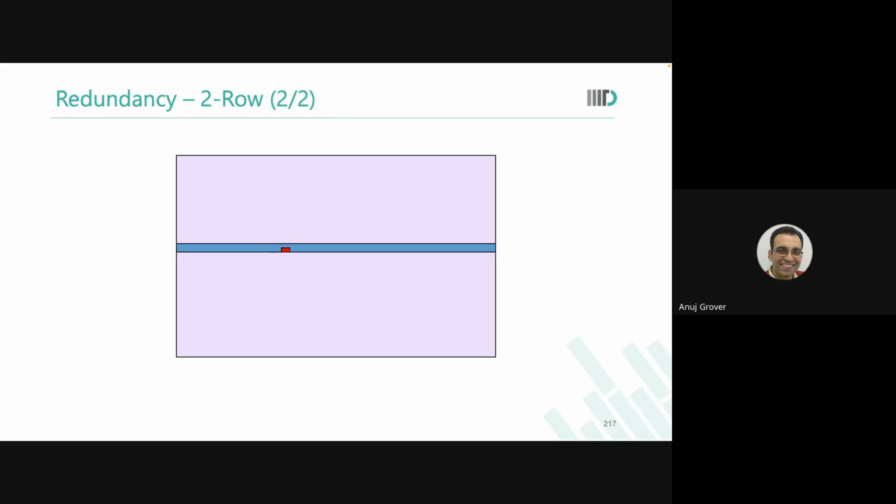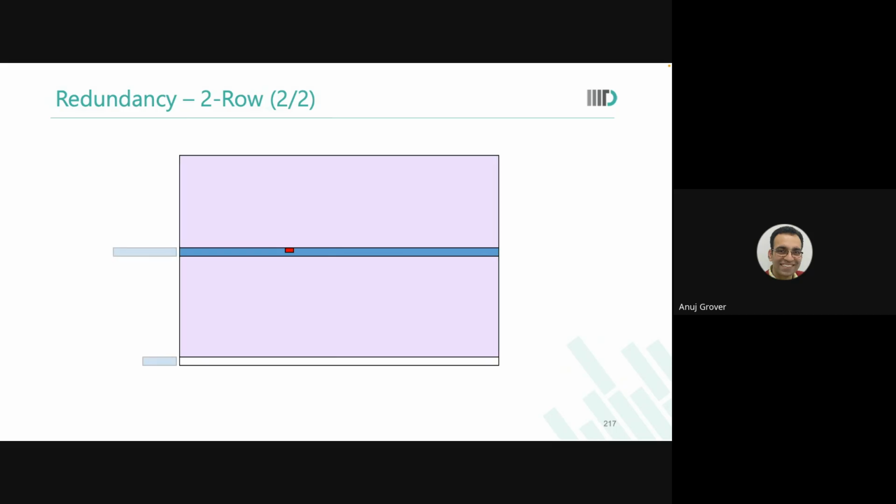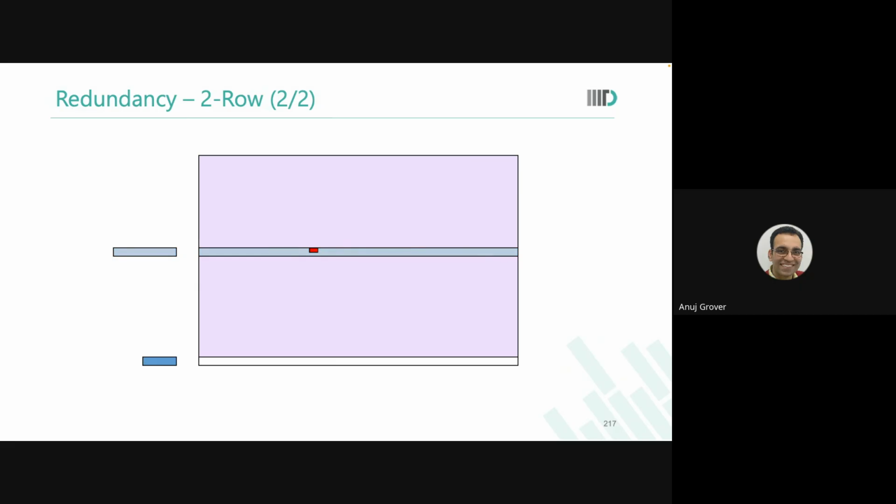It means that if this is the red bit which is failing, I should be able to replace this red bit with an alternate row somewhere. So when I'm talking of row redundancy, for a user, this red bit doesn't even come into picture, it's blacked out. If someone sends me the address of this red bit location, instead of going there, I will select this repair element. Are you getting it?